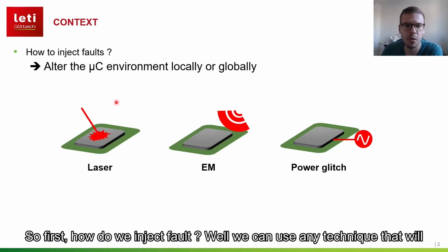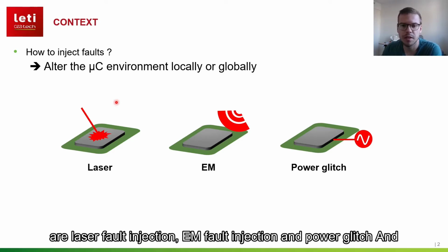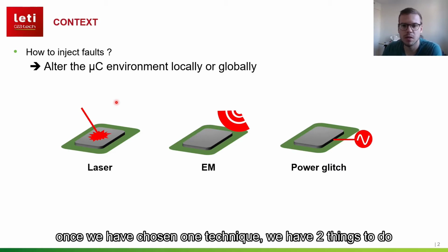So first, how do we inject fault? Well, we can use any technique that will alter the microcontroller environment locally or globally. The most popular techniques are laser fault injection, electromagnetic fault injection, and power glitch. And once we have chosen one technique, we have two things to do.